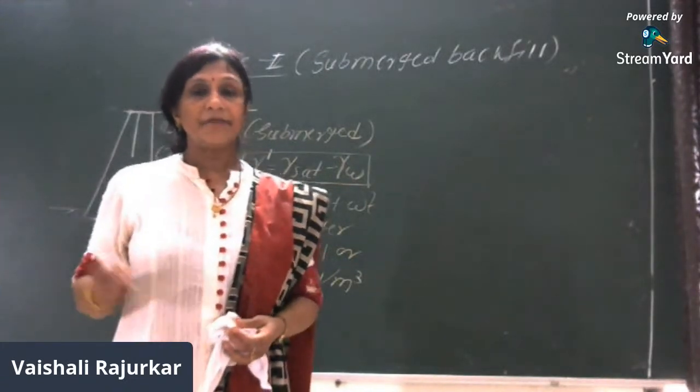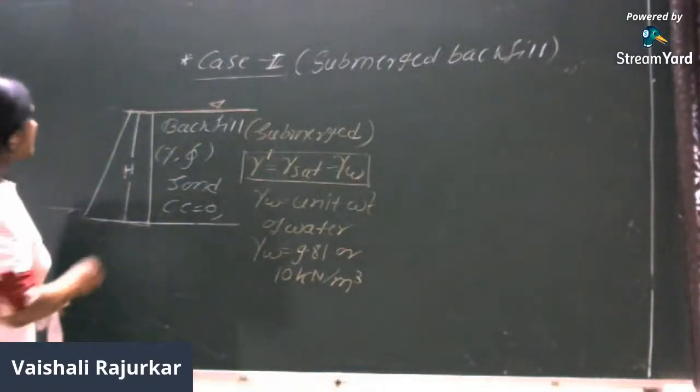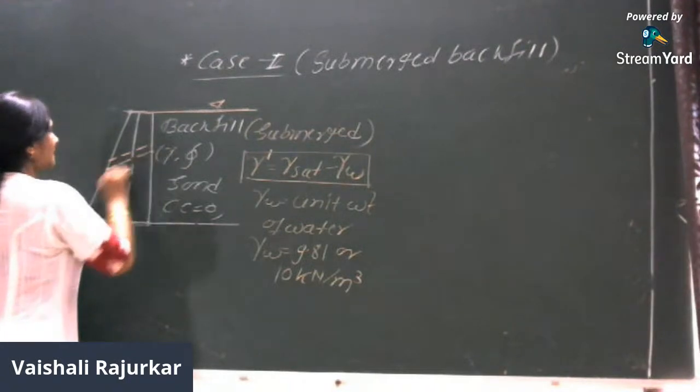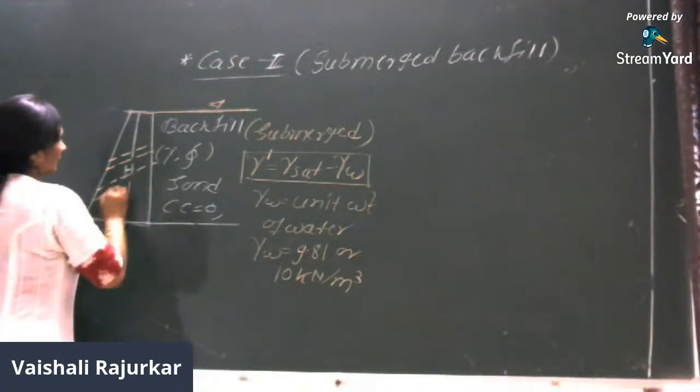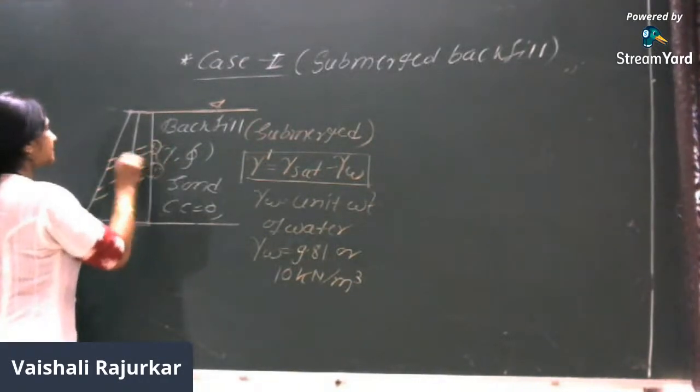And therefore, we are always trying to lower the water table, and therefore weep holes are provided here. These weep holes are provided with inverted filters.